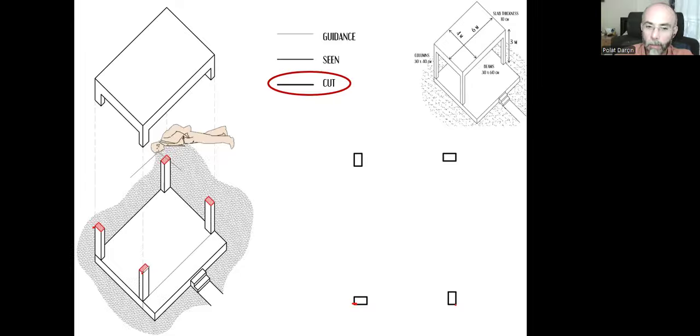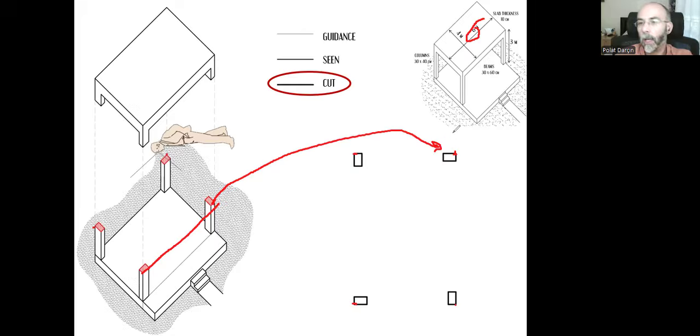And then starting from this point, I need to go this time 6 meters upwards. That will give me the third outer corner here. That's the one. And position my column like that. And for the last corner, this outer corner of this column, I need to go 4 meters one more time in this direction towards the right side and position my fourth and last column with thick lines. So you can do it with me.